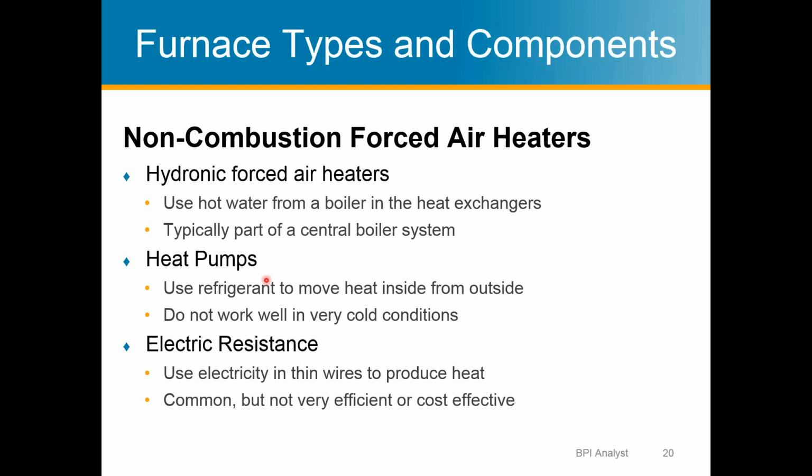But even in heat pumps, below 10 degrees or below zero, heat pumps have electric resistance backup. So if it really drops below a temperature that the heat pump itself isn't working, the electric resistance will kick in and get you through that period. Of course, that's more expensive, but even in most places in the United States, it's not going to be below 10 for too long a time. So the heat pump will work well and will be the primary source of heat.